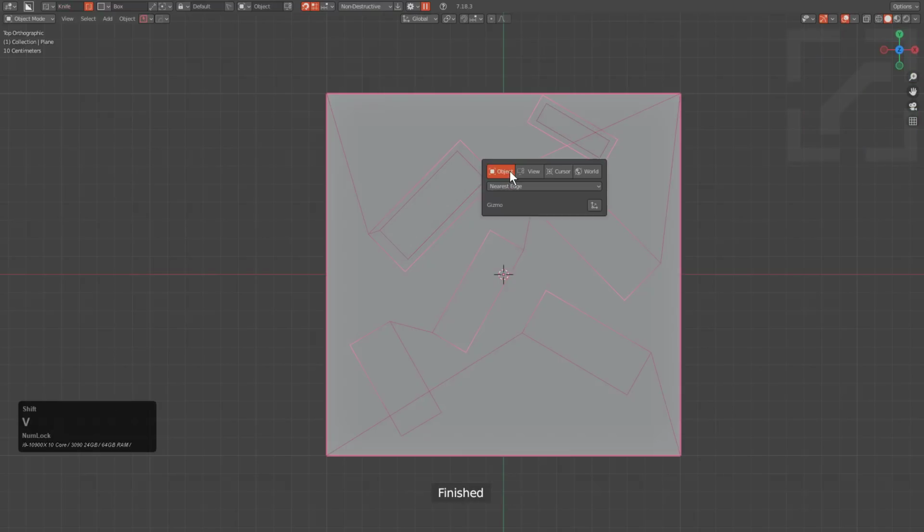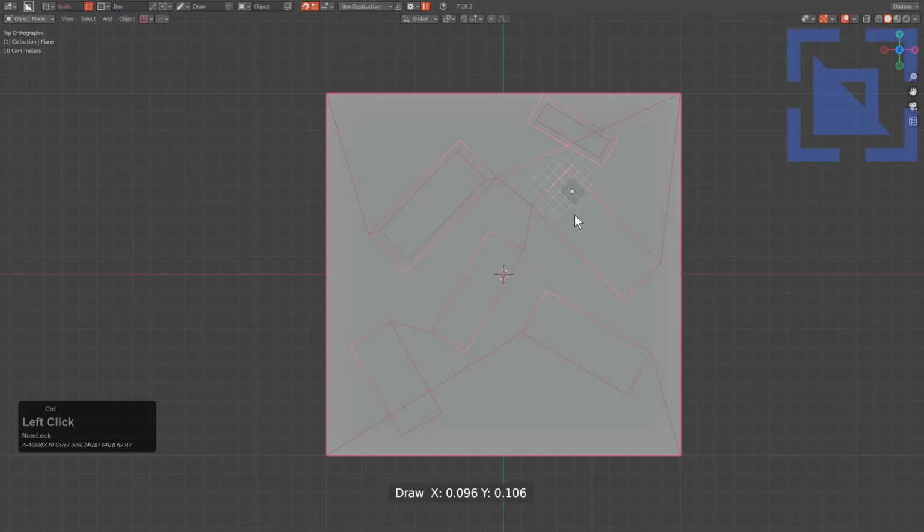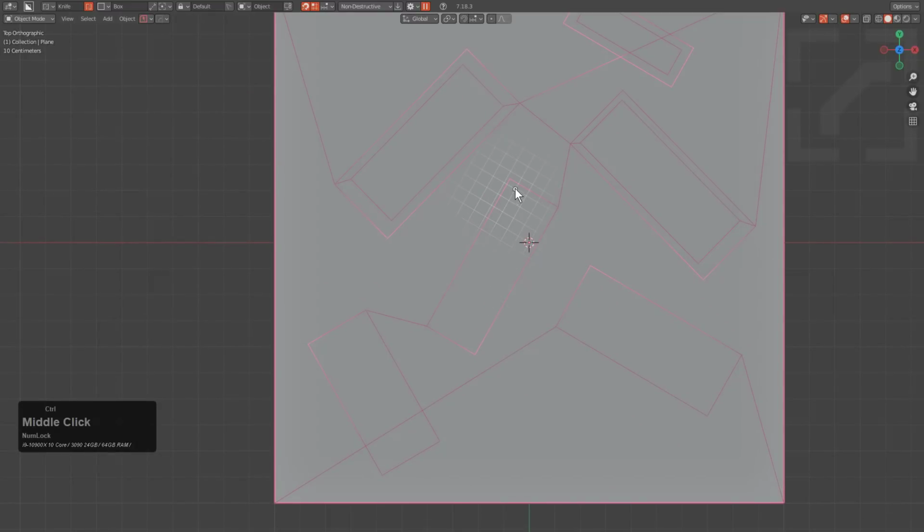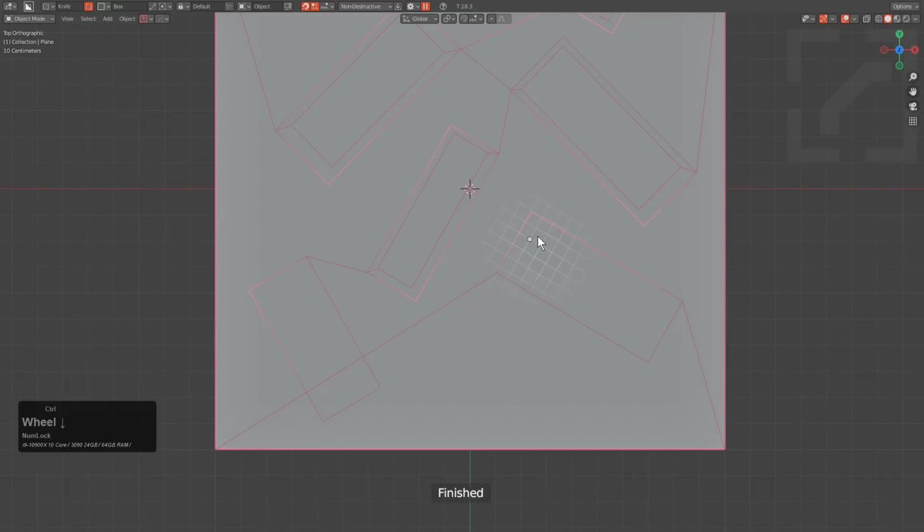However, a new mode has been added under Shift V called Face Fit, where whenever enabled, we'll attempt to orient the grid similar to nearest edge, except it's actually orienting it according to the face that's inside. If we go back to this area, we see that it's being calculated based off of this face that's underneath the cursor. Same with this one, allowing us to get an even better orientation than the one you might have been used to previously. It is a new system to Boxcutter.